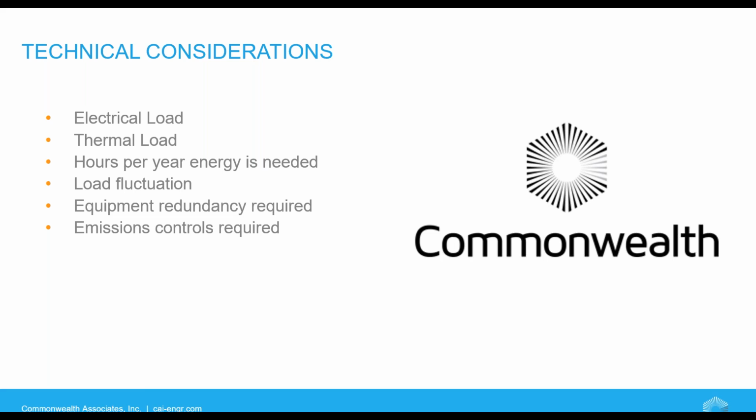From a client's perspective, if you're evaluating CHPs and if it's viable for you, I'd like to talk about a few technical considerations that you could research and take into account to evaluate if it's warranted for your situation. First technical consideration would be electrical load. Since different types of CHPs can efficiently provide different power outputs, understanding what the electrical load needed and what is required will help determine which CHP technology may be used.